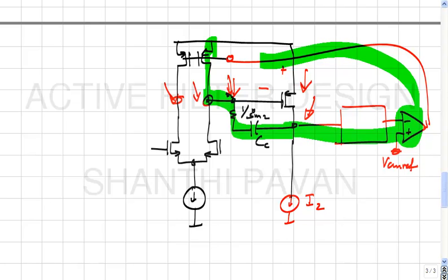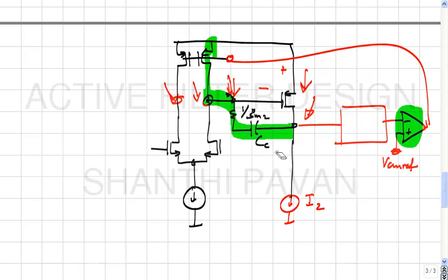Okay. Yes. We don't worry about common mode rejection ratio in the second half because we assume it's been rejected in the first. Yes, yes. So that's a good point. The question is why common mode rejection is not important in the second transconductor? It's not important presumably because the first stage has already rejected most of it, right. So, alright.